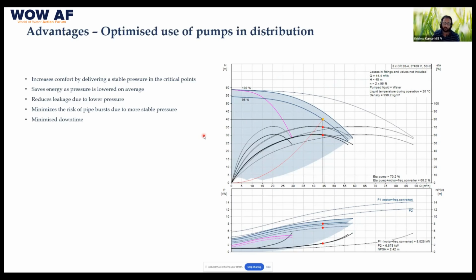Only when you learn from a complaint which says that this is where the water is leaking and it is coming out above ground. So then only you will know that this is the place where the pipe burst occurred. Otherwise, if it is a minor one and underground, only when the sinkholes happen will you know this is where it has happened.